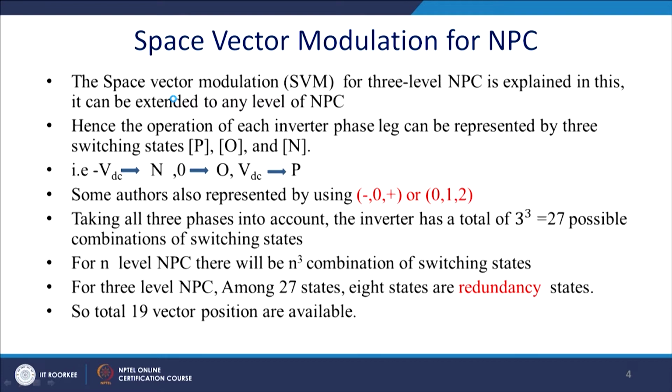Now we will implement the space vector modulation. The space vector modulation for the 3-level NPC will be explained here and can be extended to any level NPC. Students are required to understand it, and questions can be given for higher level NPCs also. The operation of this inverter phase leg can be represented by different notations. Different books follow different notations, so we try to incorporate all of them so that students do not get confused.